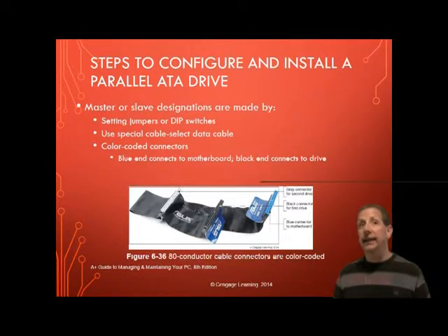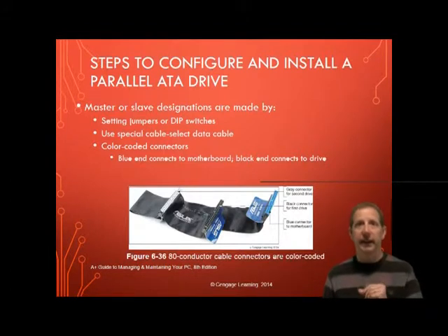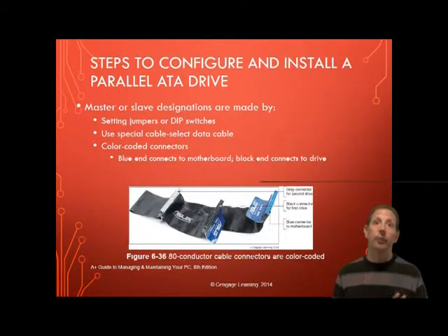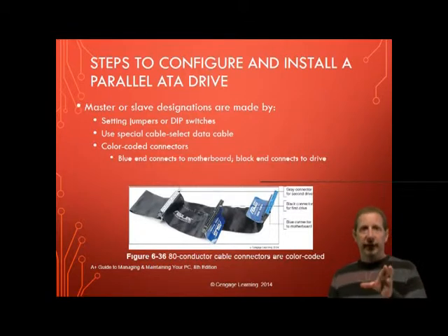The primary IDE channel, master device; primary IDE channel, slave device; secondary IDE channel, master device; secondary IDE channel, slave device. Now, the master or slave designations are made by setting jumpers or dip switches on the devices, or by using a special cable, a cable select data cable.